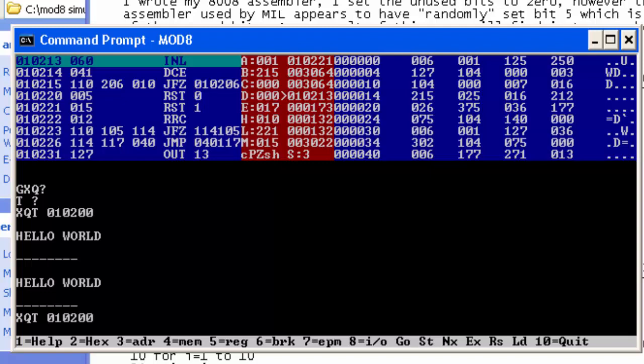You take the hex output file of that, and you can directly read that into this simulator so that you don't have to code anything in. Once it's in the simulator, you have the capabilities of running the program, single-stepping through the program, modifying registers, modifying memory values, and simply playing with this extremely powerful tool.